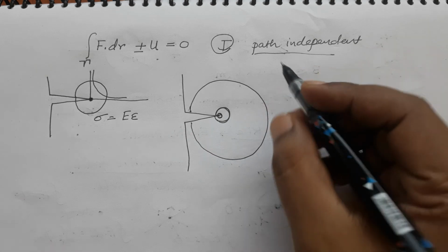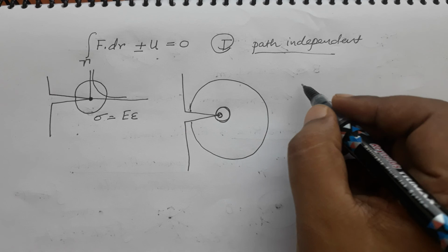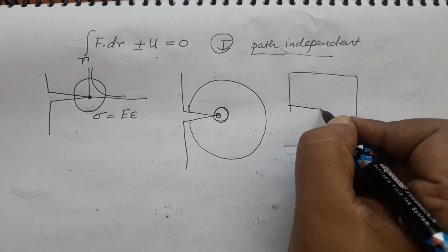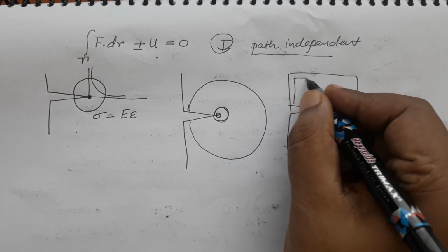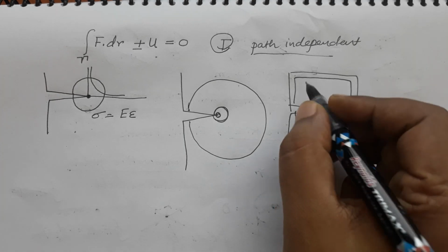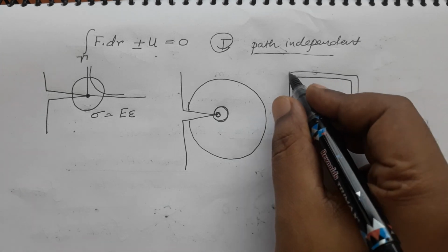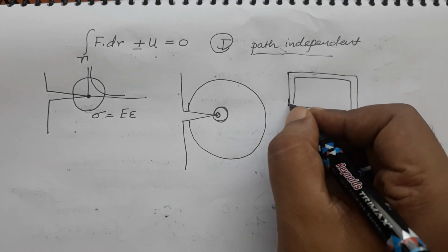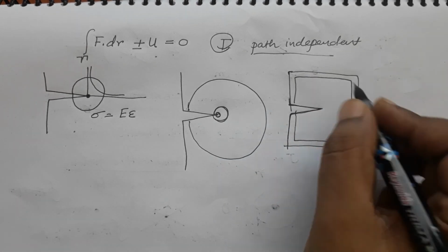Okay. So it is not necessary to have a circular path, you can take any path. Okay. So in a CT specimen, you can take a path which goes like this. You have to avoid the surface, you have to avoid the boundaries, because boundaries are difficult mathematically, okay, because there are a lot of things happening at the boundary, so we do not want those things.